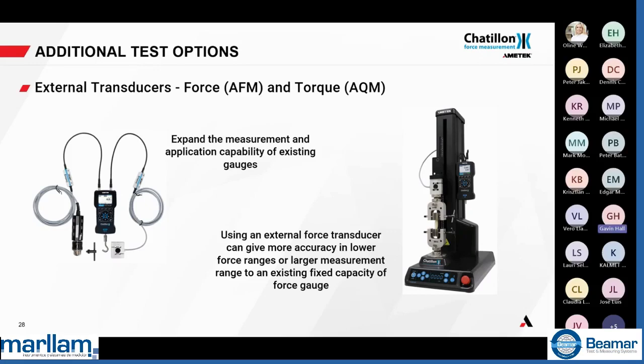Kenneth, again, thank you. Can it measure and compensate for its own deflection? No, there is no compensation in this frame. The CS is the nearest competitive frame to this, and that does have deflection compensation. So you have to be aware that there will be an accuracy budget for the TCM when being controlled. So be careful on what type of application you're going after. Typically, if the movement is going to be below 5 millimeters, it would probably not be best for this type of machine if you're looking to measure extension from a product.